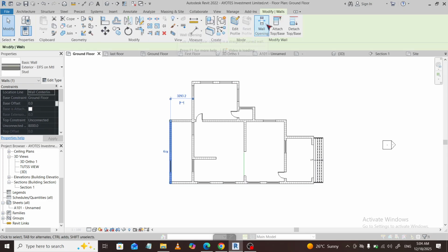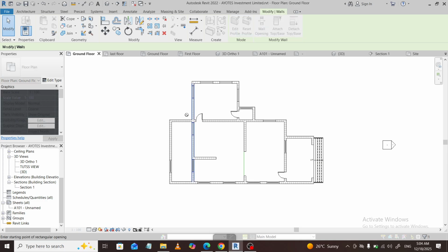Next, click the wall you want to cut. You're essentially telling Revit which wall will host the opening. If your cursor highlights multiple overlapping elements, tap the Tab key to cycle through until the correct wall is pre-selected, then click. If the wall isn't selectable, check that the view isn't cropped too tightly and that the wall isn't locked by a design option or work set permissions.